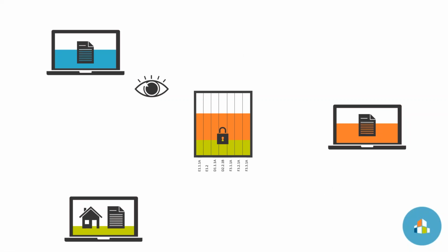Not all of the people that are involved in a project have the rights to edit a parameter. We can coordinate that with the roles and rights, so that's what you see in the middle of this picture. We can lock different parameters and say that no, this is only for the architect, for example, to edit, or some other consultants. The external consultants will add their information, but they can always view the other information that is in the database.